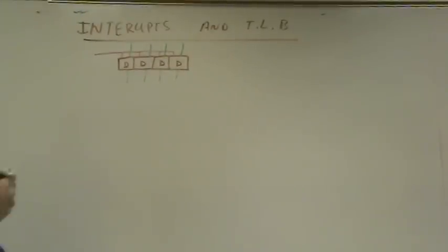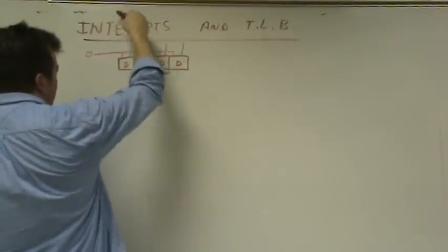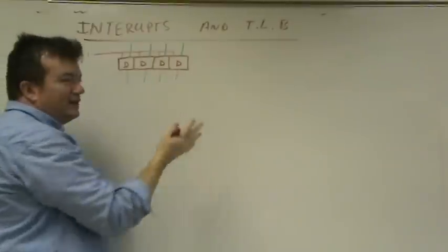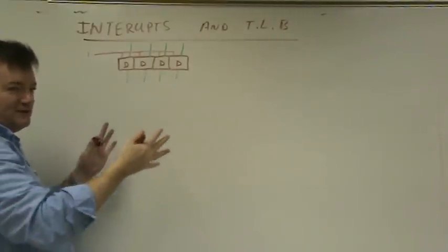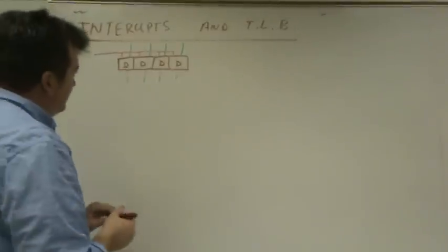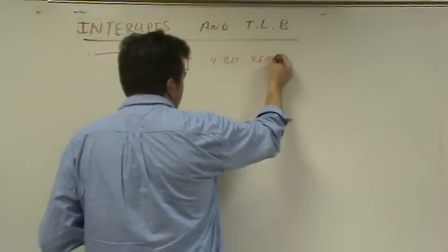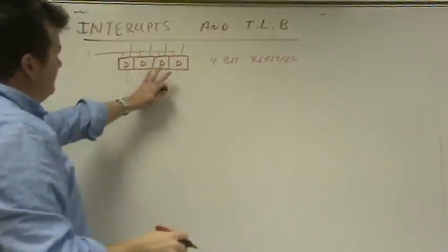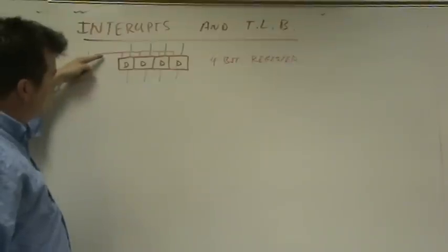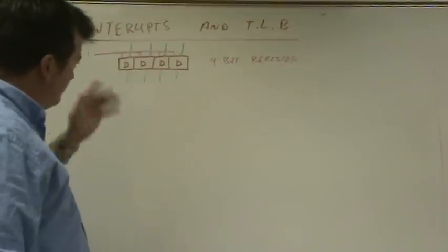Okay. So now I can set this to 0. That would allow the inputs to flow in. And then if I set this to 1, it locks the whole set of them. So really nothing new here. We're just treating them as a set now, and we open and close them as a set. So this would be considered a 4-bit register. So we're grouping D flip-flops together, and then the open and close input gets grouped together into 1 wire. Okay, and then this will stay whatever number we want it to be.